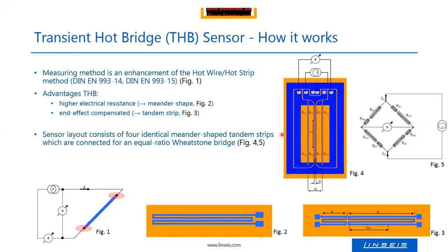And in our setup, it is self-equilibrating because the bridge is not in the electronics, it's in the sensor. And before the measurement, every wire is at the same temperature. So these resistances depend on temperature, and if all the four wires are at the same temperature, then our bridge is equilibrated, and then we can start.